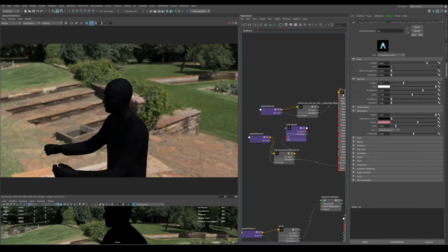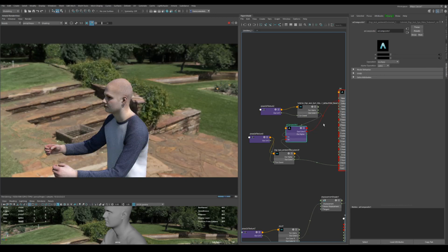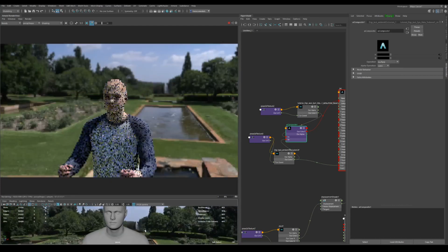So if we just turn this off, go back to colour and put colour on here, that way we can add some ambient occlusion to our map. Which will help with some baking in some shadows, basically. You just gotta set it to the multiply, which will get rid of the white and only show up the dark points.